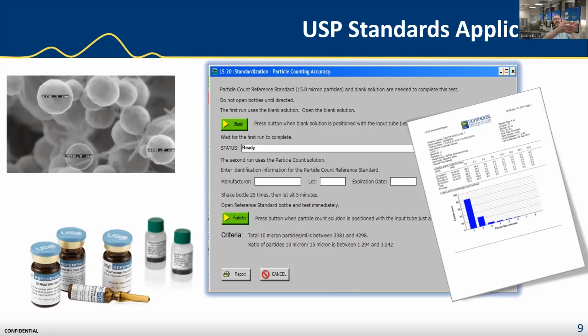When we start getting down to smaller sizes, we switch over to a light scattering technique, which is a slightly different technique altogether, which uses the scattering effect of the light on the photodetector to give us the pulses of the amplitude changing from a particle light source, which connects to the photodetector. It basically transforms that into a digital signal that the sensor can read.